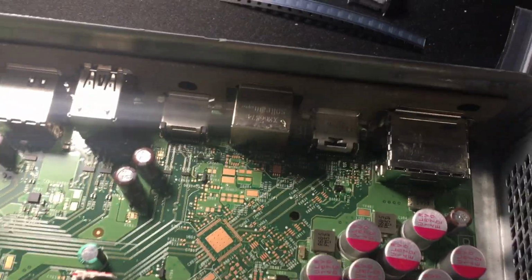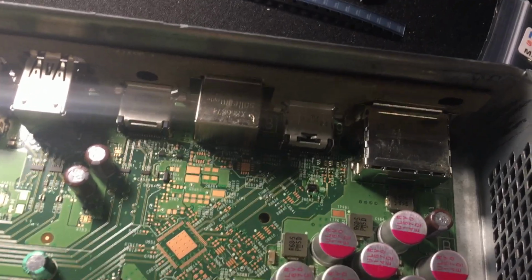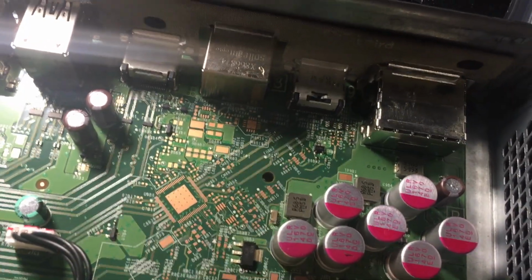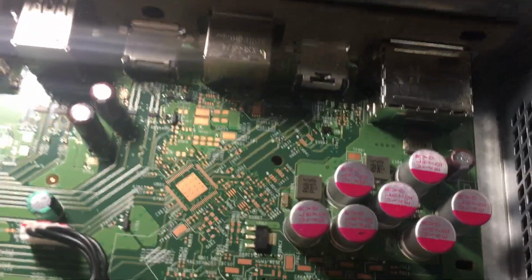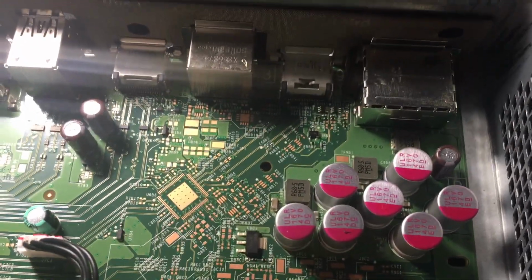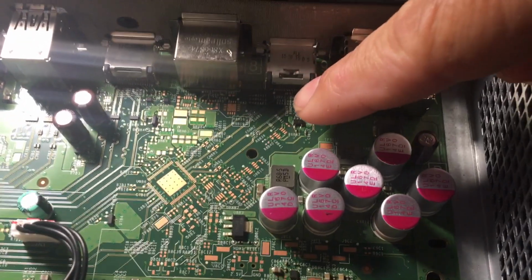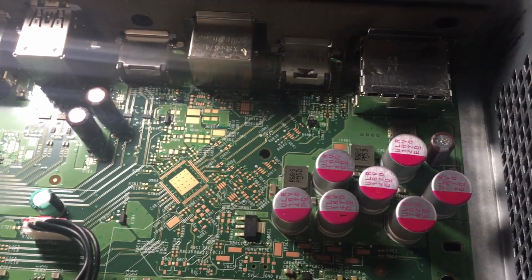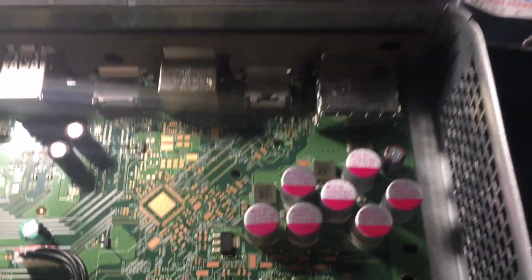So I will be offering that service on eBay for anyone that's having, and again, I'll show you later in the video the type of issues I'm having, but anybody having video output problems, this is potentially a fix. I can replace the HDMI port for only about $5, and like I said, I had to replace both filters because they tested poorly, and that's about $1 worth of parts.